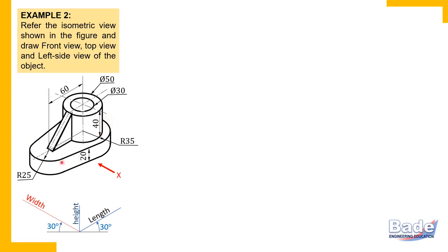When circular edges are at the ends, then generally distances are given between their centers. So from the center of this curved edge and from the center of this curved edge, which has radius 35, watch here, it is mentioned here, from this point, center to center distance is 60 millimeters.